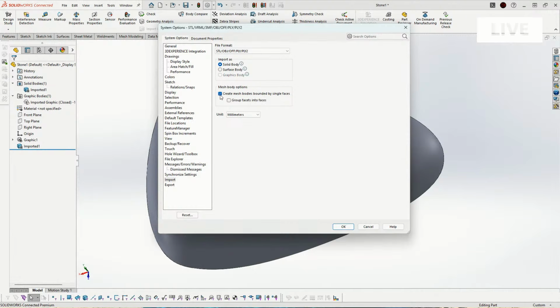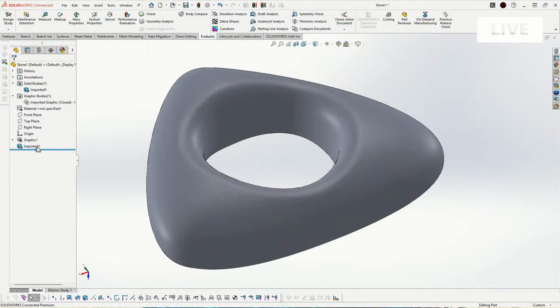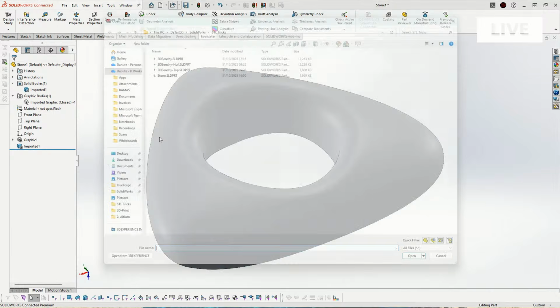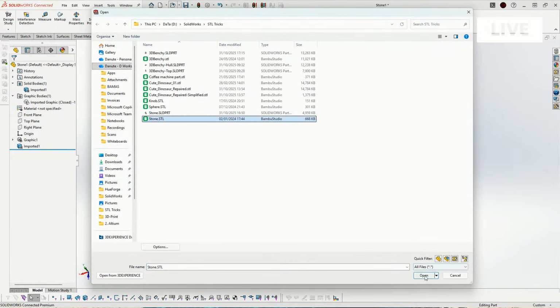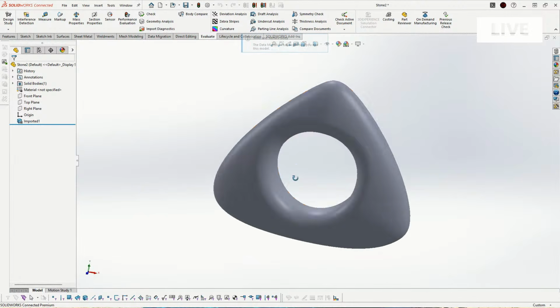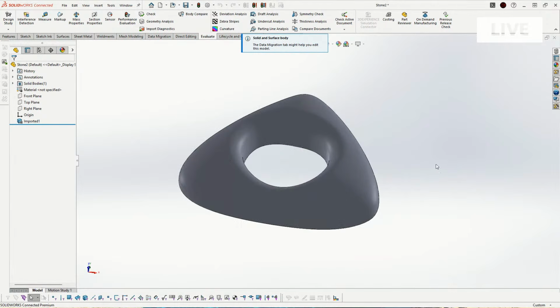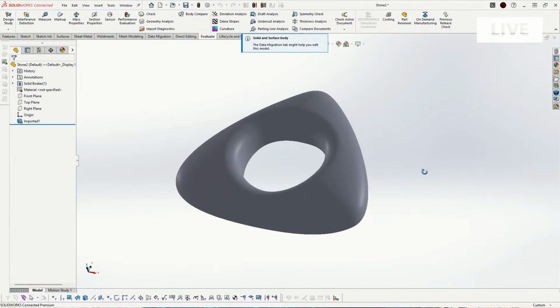If you check that, and of course you can check this too, SolidWorks is automatically going for you from graphic to imported mesh body. Okay. And you will have a file which is just with imported mesh body without a graphic body inside. Let's make it. So that's kind of automating that second step that we would have done. Yes. Okay. And now you have imported mesh body.